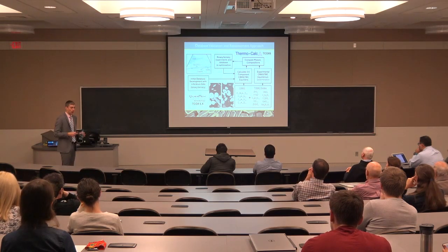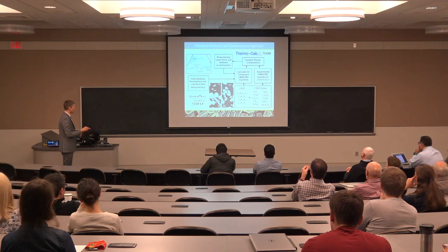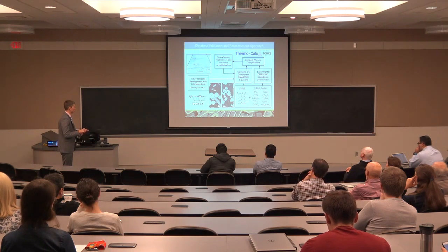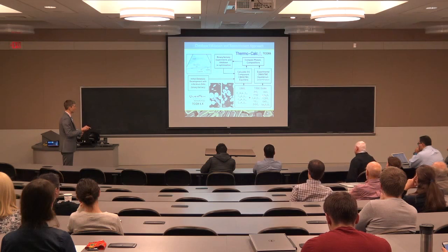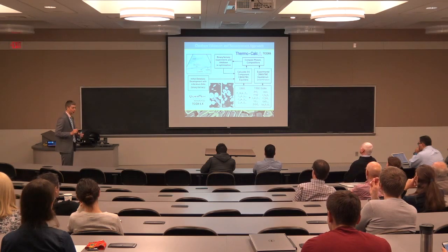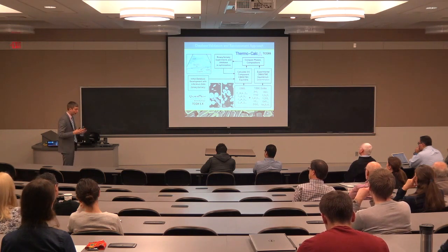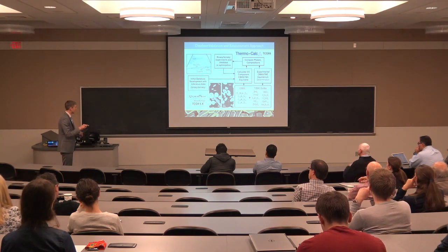To validate how well that was working in this case, we use the data from this set of experiments that I just showed, and a much broader array of experiments where we compared the behavior in these 4 different representative deposit compositions with a wide range of potential barrier coating oxides, and then measure solubility limits, et cetera, and feed this into the optimization and validation process.